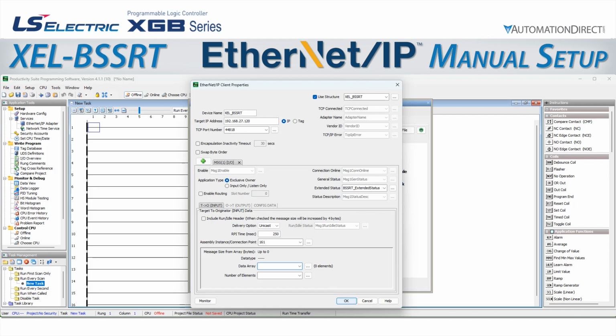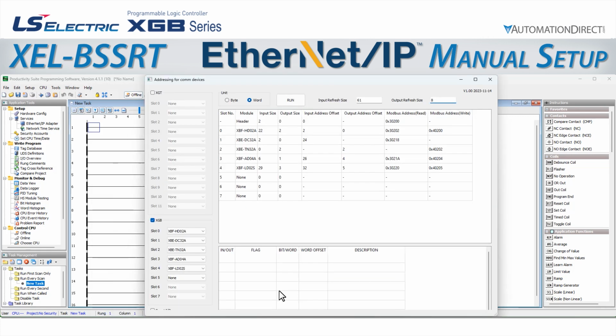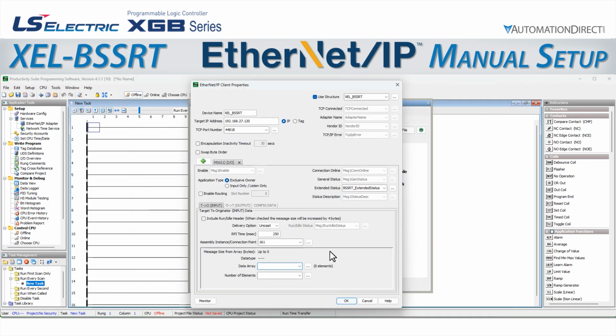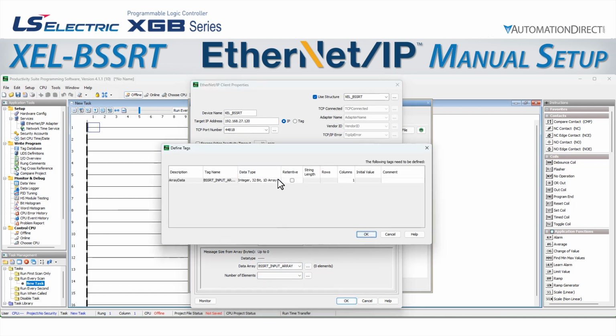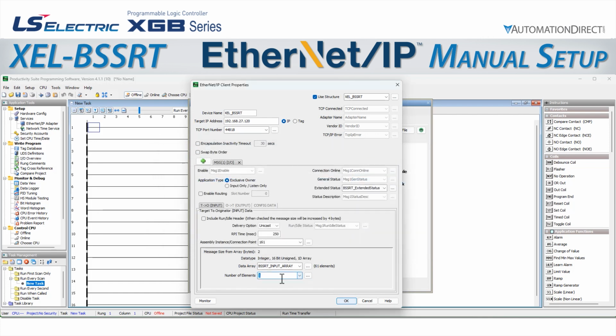To find our message data size, we go to our data addressing software tool. We set this up in the previous video on BSSRT data addressing, so please refer to it for further details. We see that for our setup, there will be 61 words of input data and 8 words of output data. Therefore, we will need a word array of 61 elements for the input. We will name our array BSSRT Input Array. Productivity will then prompt us to create this tag array before moving forward. We will leave it as a 1D array of 16-bit integer with 61 columns. This will create 61 word elements.